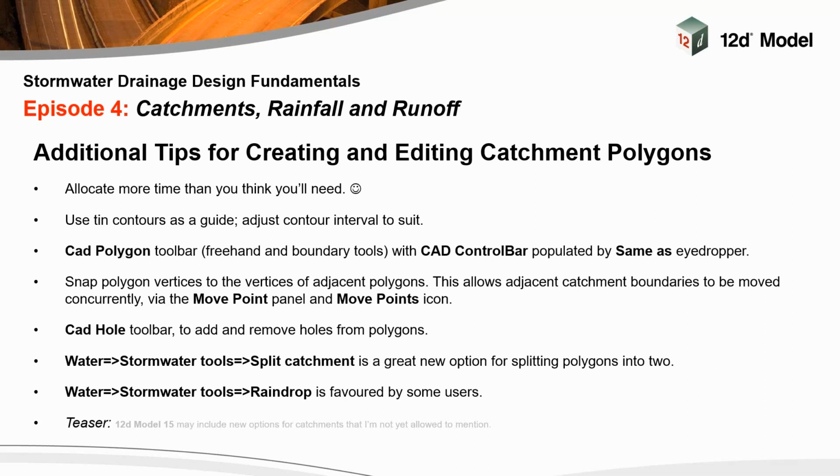One little tip that I always do that I see a lot of people don't always do, when you're drawing lots of polygons next to each other, consider snapping the vertices of each polygon onto the vertices of adjacent polygons. The reason you want to do this is, generally speaking, those polygons may need to be moved at any time in the future. If you start moving nodes around and changing designs, those polygons are going to need to be moved. And if you snap the vertices of your polygons onto each other, it means that you can move adjacent catchment boundaries together with the boundary you're actually moving using the move point and move points icon. I'll try and do a little demo of this before we wrap up.